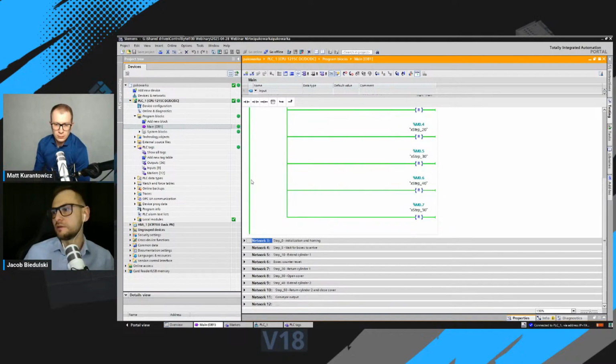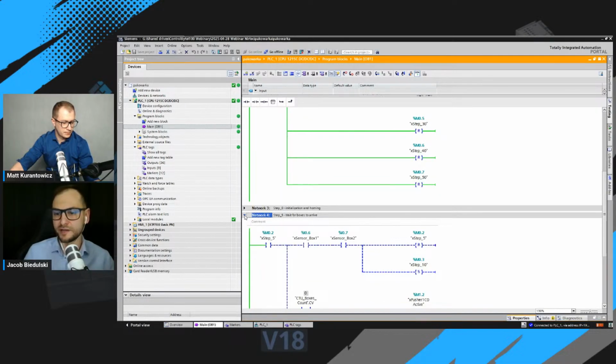Why do we number the steps by 5 or 10 or 20? Because if you name your steps with an interval of 10, it is easier to implement intermediate steps, okay? For example, we had defined step 0 and step 10, and after a while of coding, we decided to insert an intermediate step, and it was step number 5, okay?